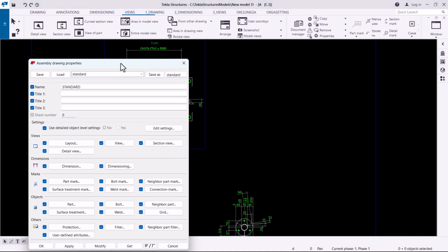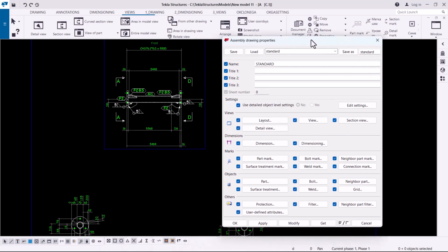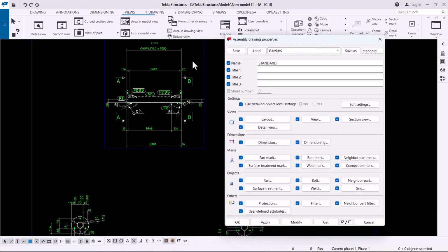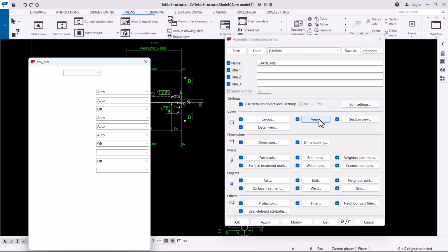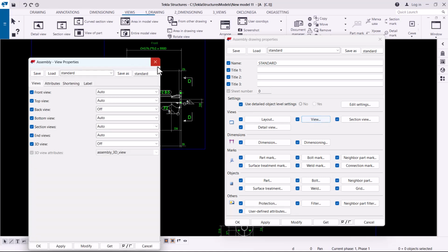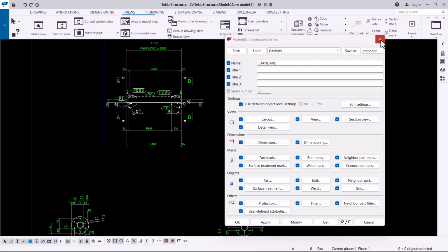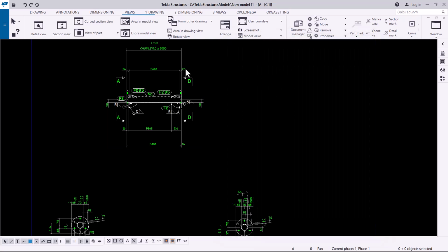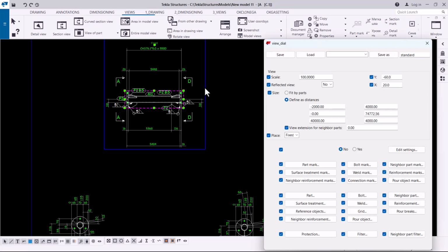So in here, I want to change the scale. But remember, if we just click inside, you won't be able to get that tool for scaling. Or if we come to view here, I think we can have the tool for scaling, I suppose, but it is not. So the best way always, when you mouse over this and you see this blue boundary, just mouse over and double click by left clicking on the boundary. Just double click on the boundary like that and give some time to load that information.